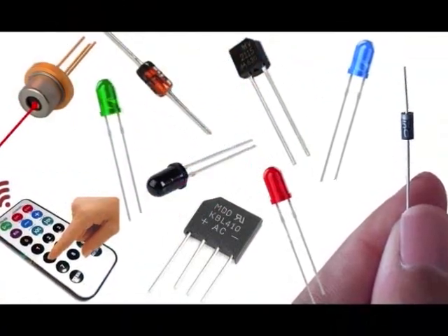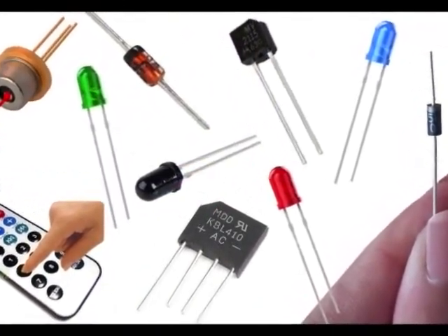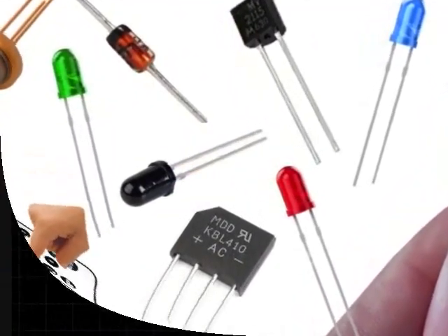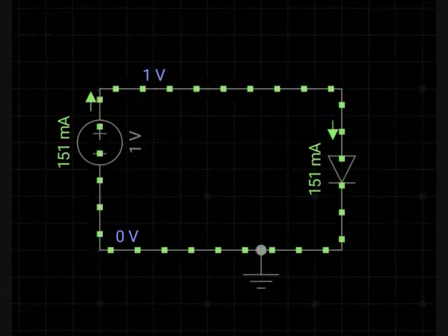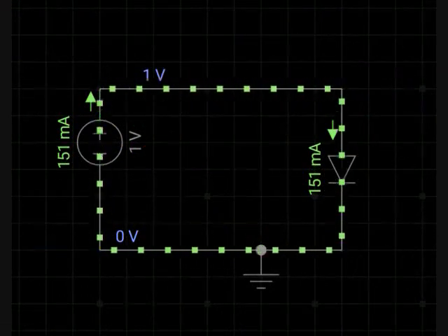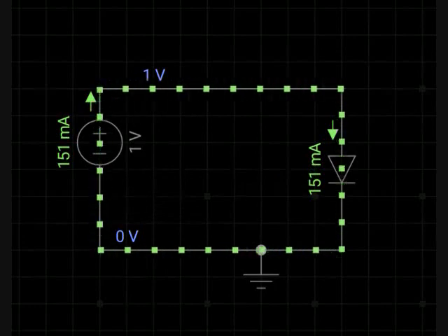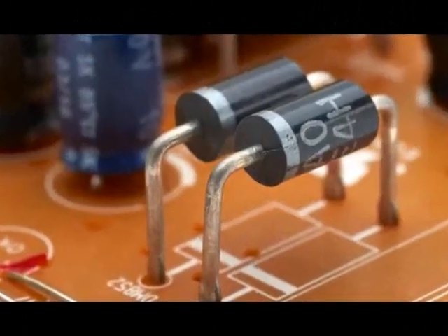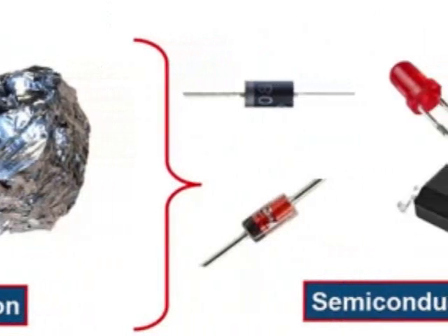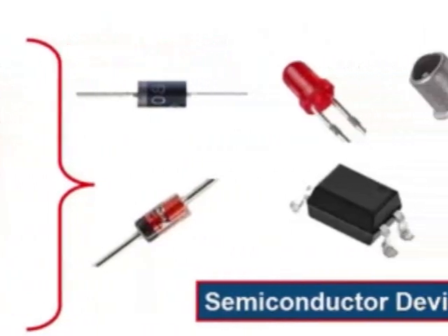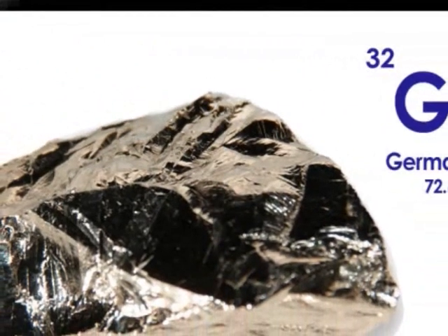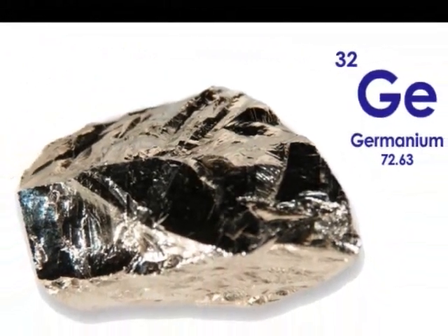A diode is one of the types of semiconductor parts that are used in many electronic circuits, and it conducts the electric current in one direction and prevents the current from passing through the circuit in the opposite direction. In fact, a diode is a two-terminal valve that moves current in one direction. These parts are made of various semiconductor materials such as silicon or germanium. They are formed by connecting two impurity regions, P and N.